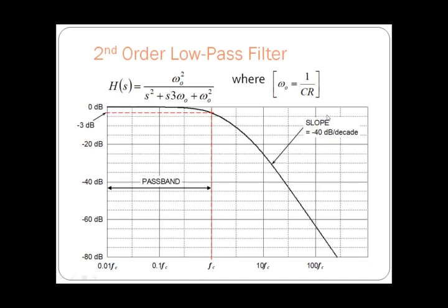So the actual response will be like this, but practically we are getting the response which has shown in a black line here in this graph. So we are going to reduce this curve, that is attenuation. We are going to bring this attenuation line towards FC. So this can be done by considering number of RC networks.